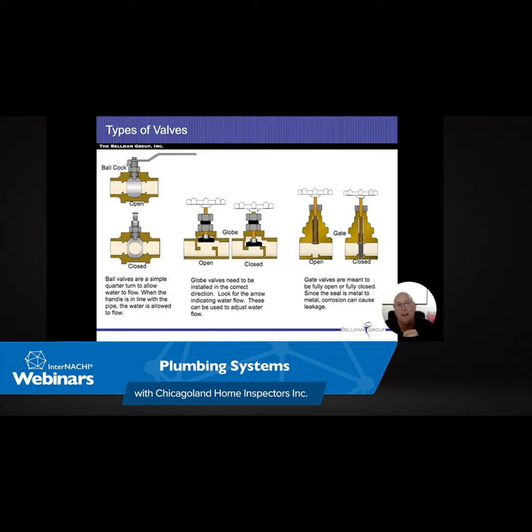But as we look at the bottom of that where it goes down and I got that U shape and then it comes over and turns towards the back, that's the rear of the trap, all right? That's supposed to go straight into the wall. But instead it turns back up again and then it turns right and goes into the wall. So in all reality, everything that's level with that pipe that's going out of the right is going to be filled up and held with water. It's just going to start creating problems with drains, low water flow, clogs, everything else that comes with it.